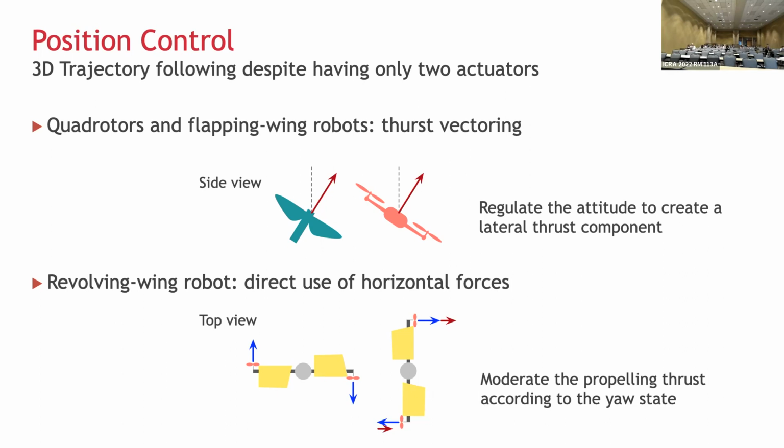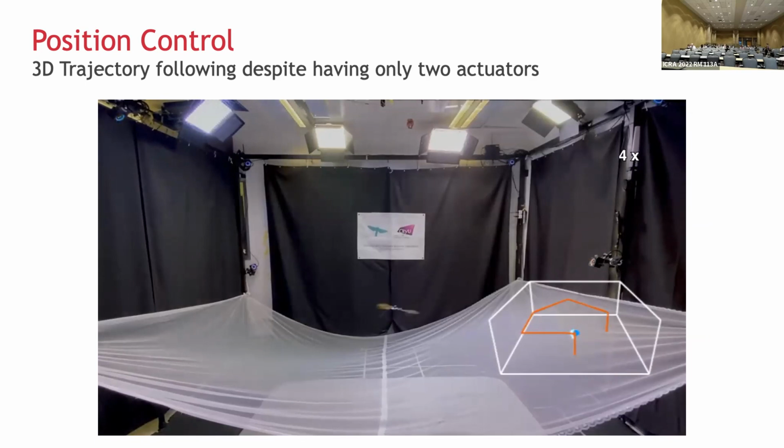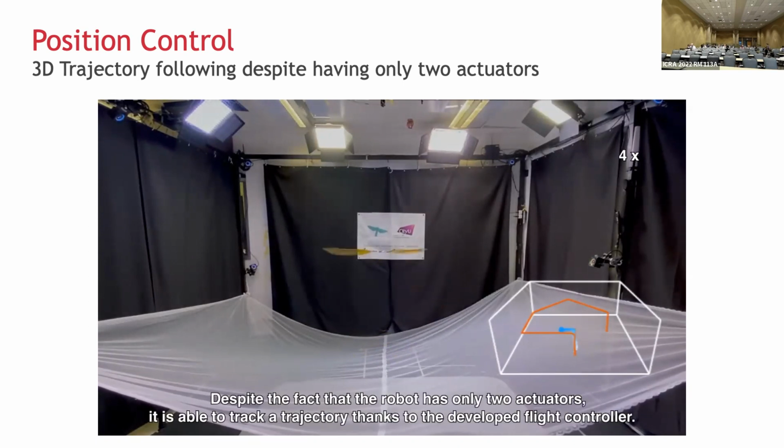For our robot, we can actually use thrust from the propeller, which is pointed horizontally, to move the robot sideways directly by timing how we actuate the propellers, right? So despite having two actuators, we can still do 3D position tracking following a trajectory.